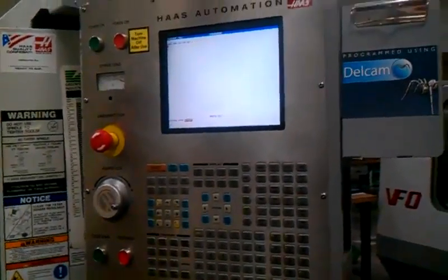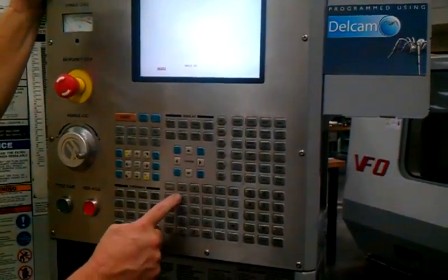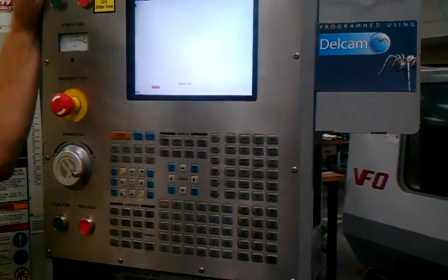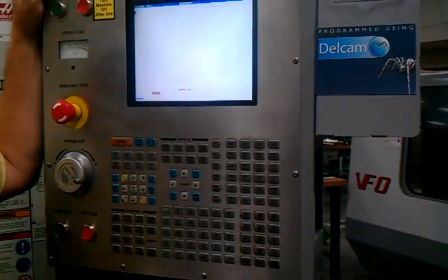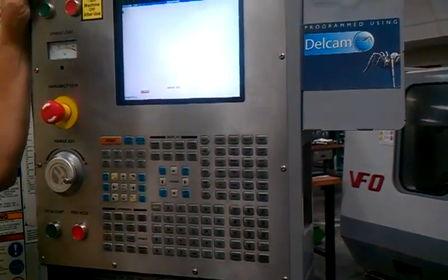Now, if I were to take that tool, I'm going to write another line of code, G43, add the offset in a positive direction, H1, using height offset number 1, go to Z 1 inch above the part.